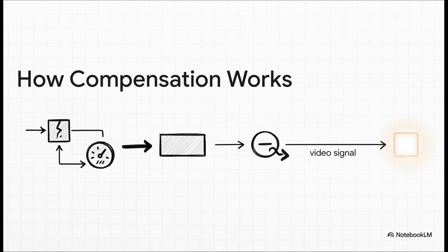During a quick little setup phase, the pixel circuit basically takes a reading of its own main transistor to measure its specific flaw. It then stores that unique error value. Then, when the actual video signal comes in, the one telling the pixel how bright to be, the circuit automatically adjusts that signal to cancel out the error it remembered. The result? The final current sent to the OLED is perfect, and that ugly Mura just disappears.